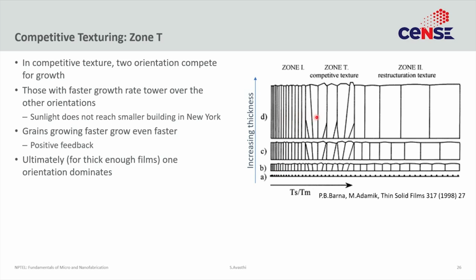So, that is actually called that the kinetics decides which growth rate will win. This is not thermodynamically decided, it is kinetically decided. The fastest growth rate wins. So, for very thick layers the fastest growth orientation wins out, so you do get some texture. But if you look at a cross section, you will actually see that difference. Initially you will see all different types of orientations. As you go further up and up, some of these orientations, you see the small triangle, lost out and got extinct, and the orientation that was growing the fastest kept growing.